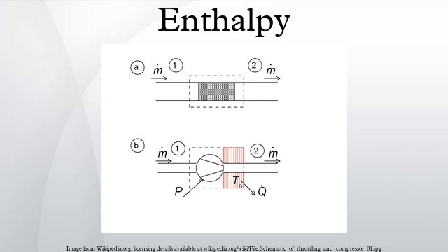One of the most common diagrams is the temperature-entropy diagram. An example is Fig. 2, which is the TS diagram of nitrogen. It gives the melting curve and saturated liquid and vapor values together with isobars and isenthalps. These diagrams are powerful tools in the hands of the thermal engineer. Some basic applications: the points A through H in Fig. 2 play a role in the discussion in this section.